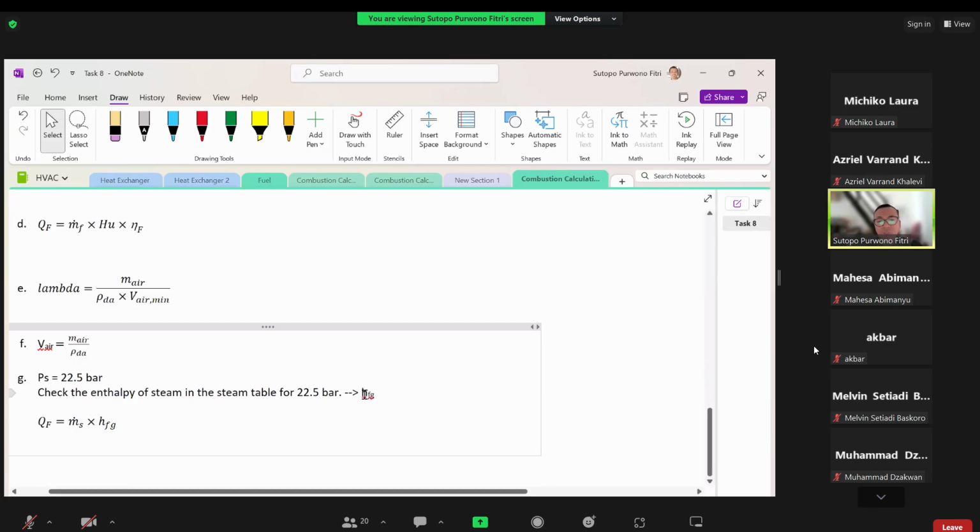So calculate the difference between the steam enthalpy and the liquid enthalpy. Then based on the known power from the firing power, you just make an equal heat balance or energy balance from the firing power. Then you can calculate the required power for defining the mass flow rate of the steam based on the enthalpy here.